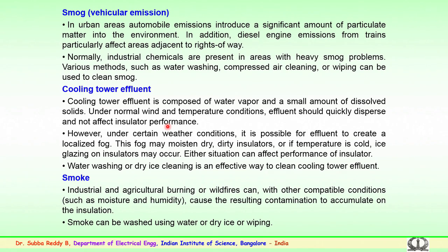Smoke, this is again due to industrial and agriculture burning activities or due to wildfires. This can result in contaminants spreading on the surface, and with other compatible conditions such as moisture and humidity can cause the resulting contamination to accumulate on the insulation surface. Smoke can generally be washed using water or dry ice or by wiping the surface of the insulators.